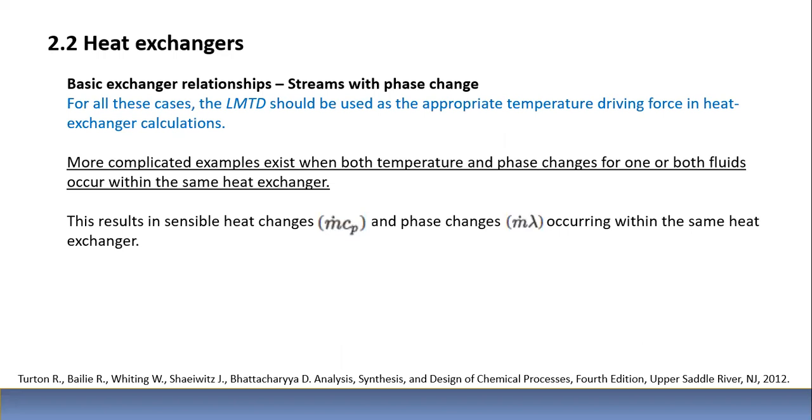For all these cases, the logarithmic mean temperature difference should be used as the appropriate temperature driving force in heat exchanger calculations. More complicated examples exist when both temperature and phase changes for one or both fluids occur within the same exchanger. This results in sensible heat changes and phase changes occurring within the same heat exchanger.